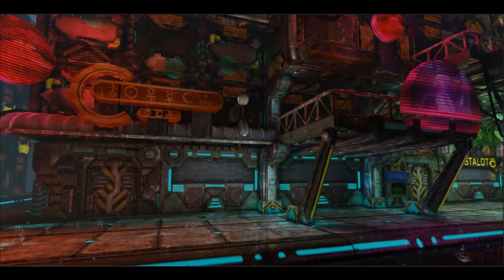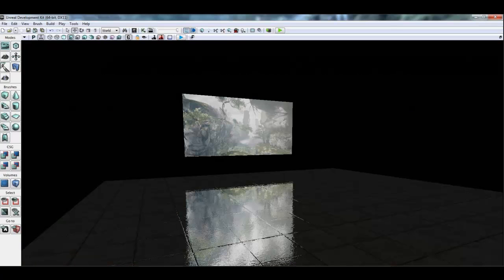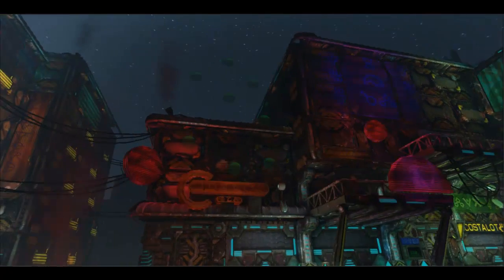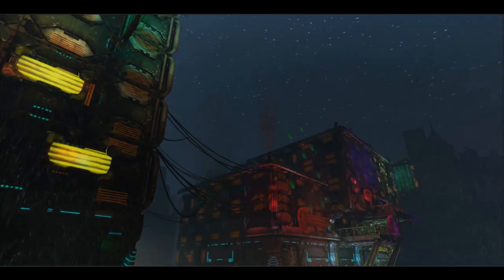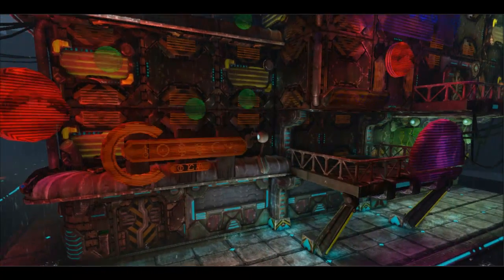The reflections on the floor use a Scene Capture Reflect Actor from the DX9 renderer. I did try and use the image-based reflection actor from DX11, but I found having to position each image actor was a lot less efficient because of the amount of reflections needed and all the overhanging construction of the building.